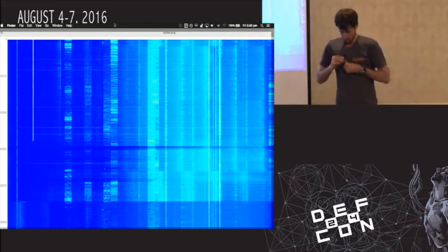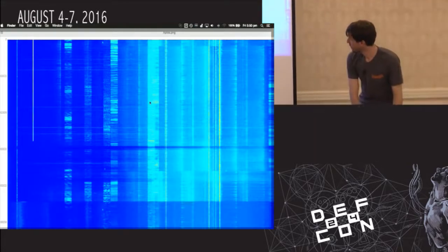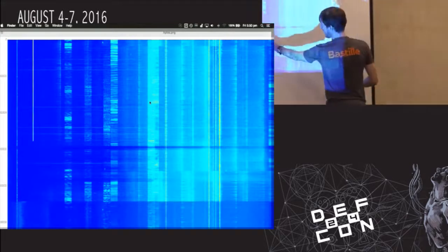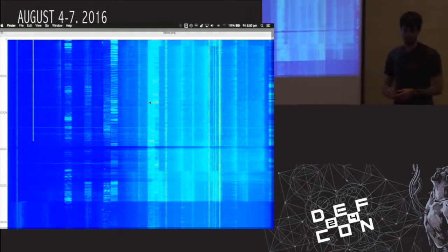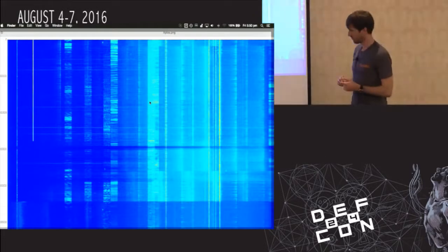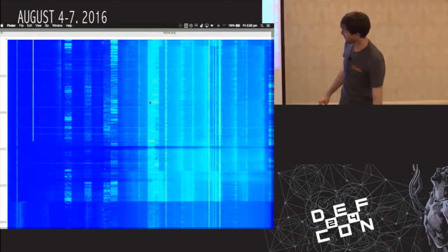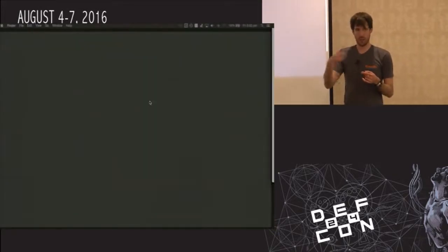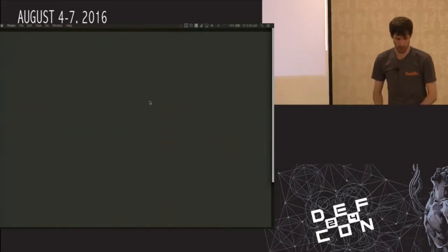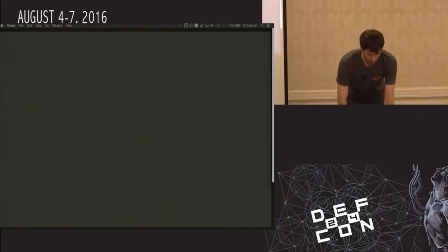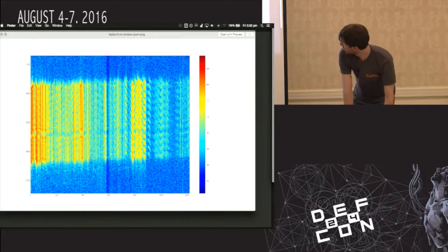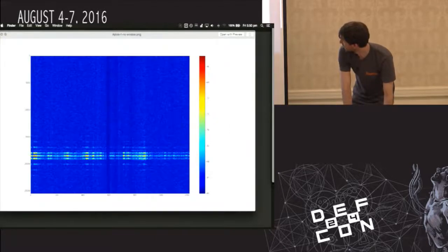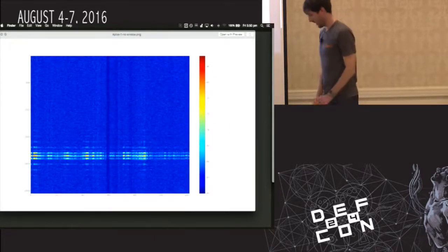And then once you do some clever processing, you can basically find the bandwidth, and then you can use some simple DSP tricks and do autocorrelation on the signal to find the rate at which it is running the chirp, because it's a repeating signal. And then you can create a matching chirp and then filter that down. So you get a plot like this, essentially.